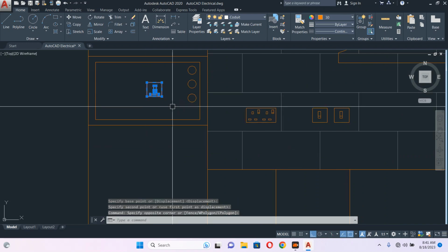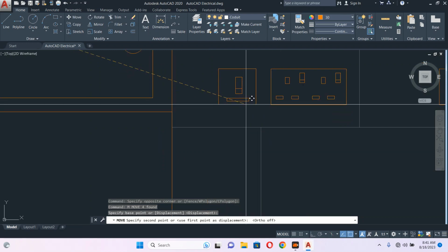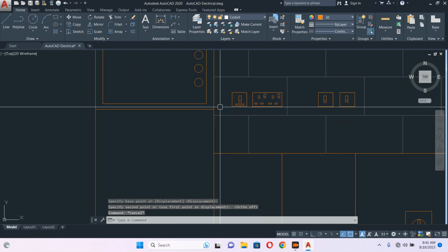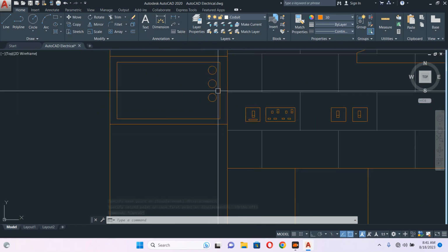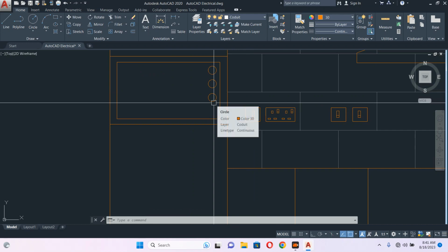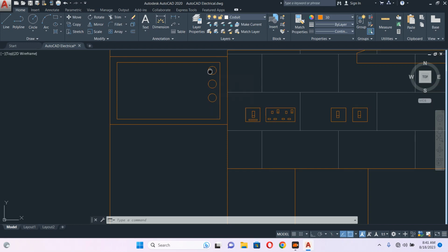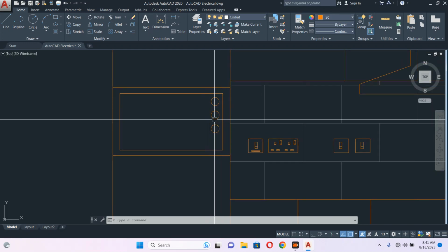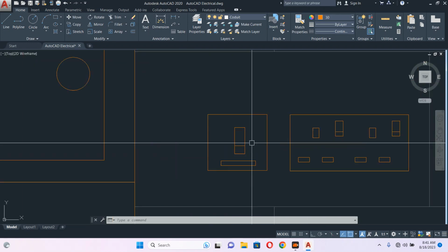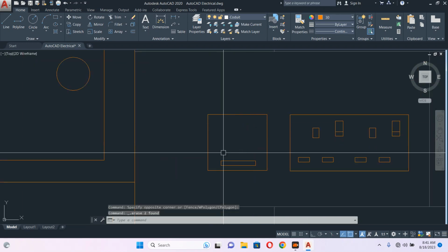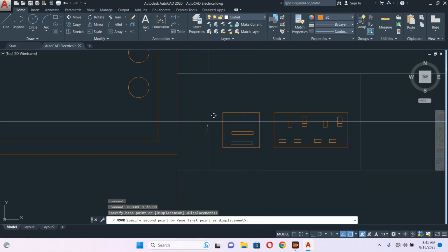Let's come to this one here. This one can be unswitched also. Why? This oven already has outlets, and already has control buttons or a control wheel to switch on and switch off. So there is no need for a switched spare outlet, you can use just a spare outlet only to provide power. So it will be something like this, an unswitched spare outlet.